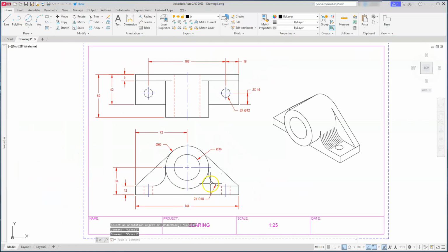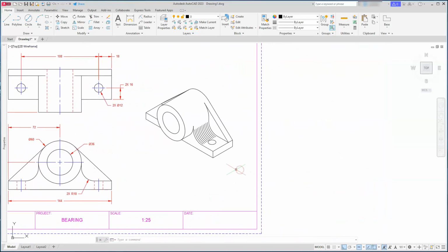Okay, so now with that being corrected, let's go ahead and start creating our isometric drawing. The first thing we're going to do is create this front face, then we're going to build this back one off of it, and then we'll have this part protruding out of it. So I want to switch to isometric, and I'm just going to click this icon, and you'll see that I'm now in isometric. This icon turned blue, and this one as well is blue. It's always a good idea to have your ortho on whenever you create an isometric, and that'll help keep your lines going in an isometric view.